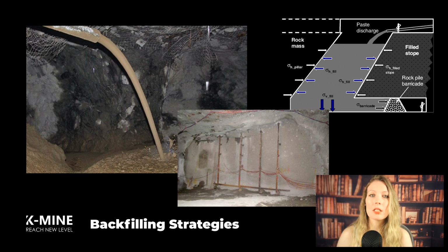Backfilling strategies also play a critical role in optimizing stope layouts. Hydraulic backfill and paste backfill methods are commonly used to provide structural support while allowing for adjacent stopes to be mined safely. Studies on backfill mechanics show that the consolidation rate and cohesion properties of backfill material directly affect stope stability.